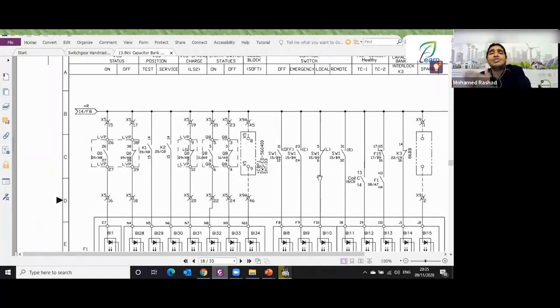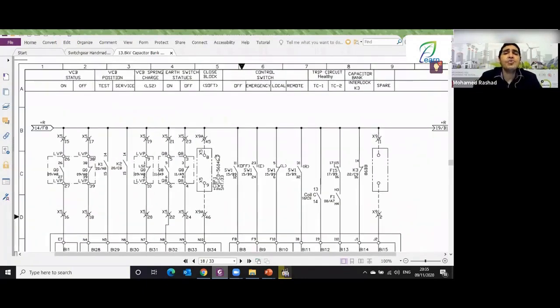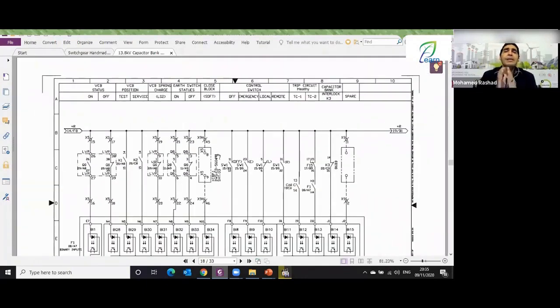And so on, anything connected to the PCB. So what should be connected to the PCB? The PCB, which is the protection and control unit, should have digital signals connected to it. These digital signals can be used as interlocking circuits, can be used for status, or can be used as alarms. What does this mean?